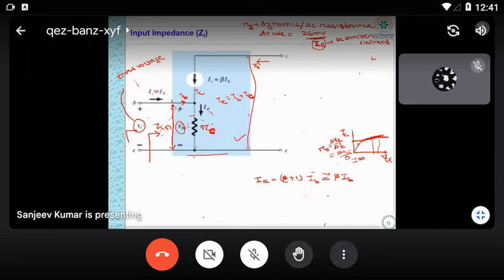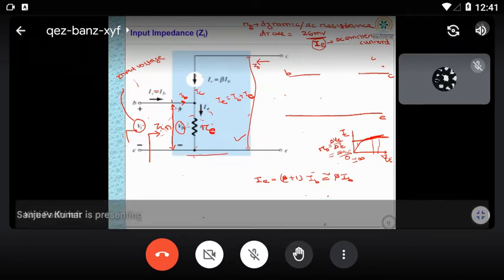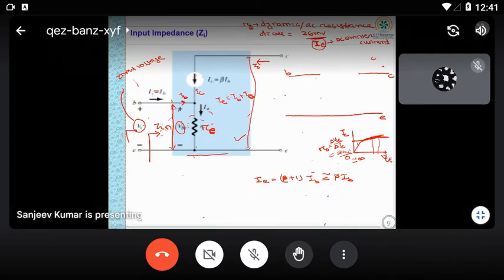Okay. So here you can see for a transistor, three terminals are there. Already you see the emitter is common, so I have taken the emitter line here. Now I can take base as one line, and base and collector I am taking as one line. Now here you can see the resistance value. It is connected from base to emitter, the input impedance. So this input impedance Zin I can write here, which is beta re.